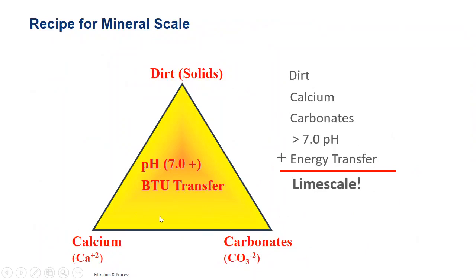Well, if you think about water softeners, we just take this ingredient out of this pyramid and it collapses. When we take reverse osmosis or membrane technologies, we're reducing this, and this to a point where they're no longer significant. They don't form enough scale to be a problem. You can also remove the carbonates. If you think of dealkalization technologies, if you're thinking about our systems friends, this would be our Claris technologies. It breaks down the carbonate and converts it to CO2 gas and gases it off.